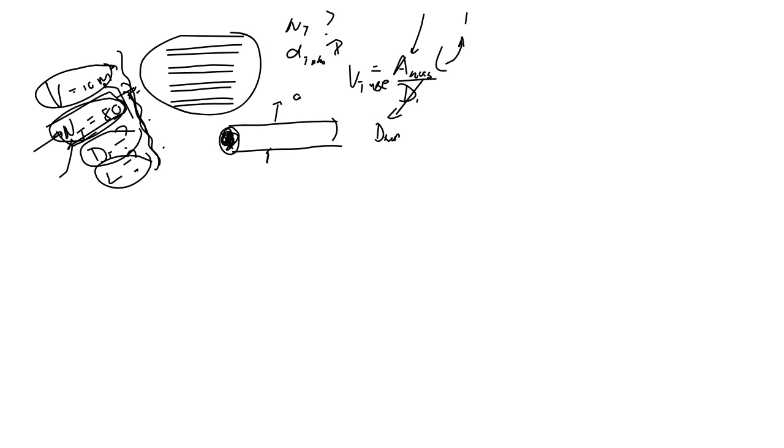Play around with this. Remember, look at realistic tube diameters. And what is a realistic tube diameter? Some design aspects here that we are going to discuss: you will base that on typical sizes of tubes that you can find. 20 millimeters, that's industrially available for the material of construction that you are going to be using.